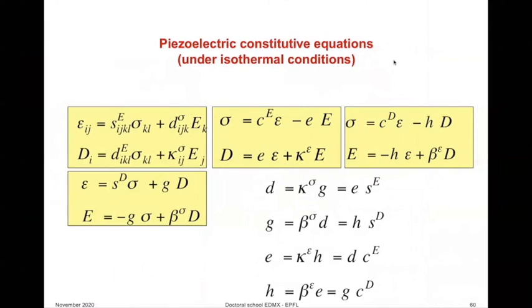When we are discussing piezoelectric experiments, we have to take into account the full piezoelectric constitutive equation, meaning that we have to take all terms that may contribute to the final response. In the previous case, I would have here also, Pi times delta T, that is the pyroelectric effect. But as I said, we usually neglect that because we can control temperature in a room and work under isothermal conditions.